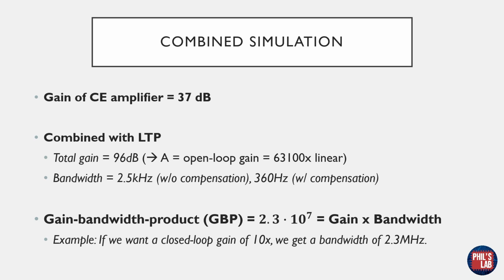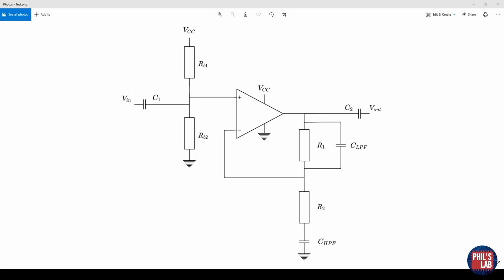Now that we've gone over a very basic design, let's have a look at the PCB and then do some analysis and tests in real time. On the final PCB, I've implemented our operational amplifier, which you just saw, but also provided some external circuitry, which we'll go through one by one. Essentially, our operational amplifier, as we saw before, in an open loop configuration is a tiny bit useless. So what I've done is first of all provided some sort of biasing structure, here shown simplified with just two resistors, to bias our op-amp at half the supply voltage, to make sure everything inside the op-amp and the output can swing to its full potential, so to speak.